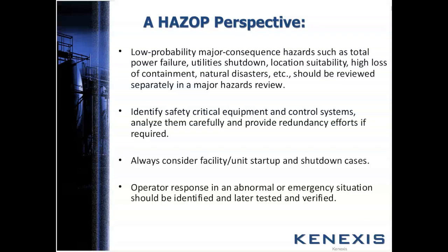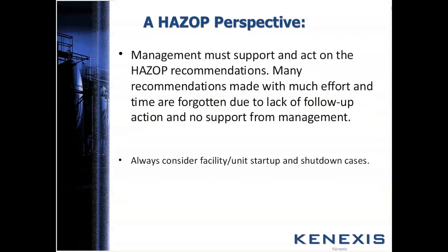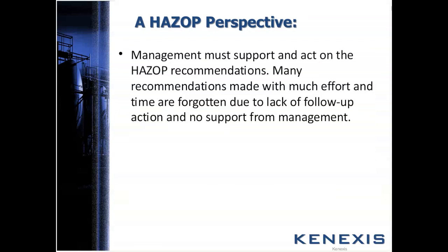And operator response in an abnormal or emergency situation should be identified and tested and verified. Okay, these are different studies. HAZOP may not be the best for those. Okay, so the major perspective: management must support and act on HAZOP recommendations. Many of the recommendations made with a lot of effort by the team are forgotten just due to lack of follow-up action and no support from their management.